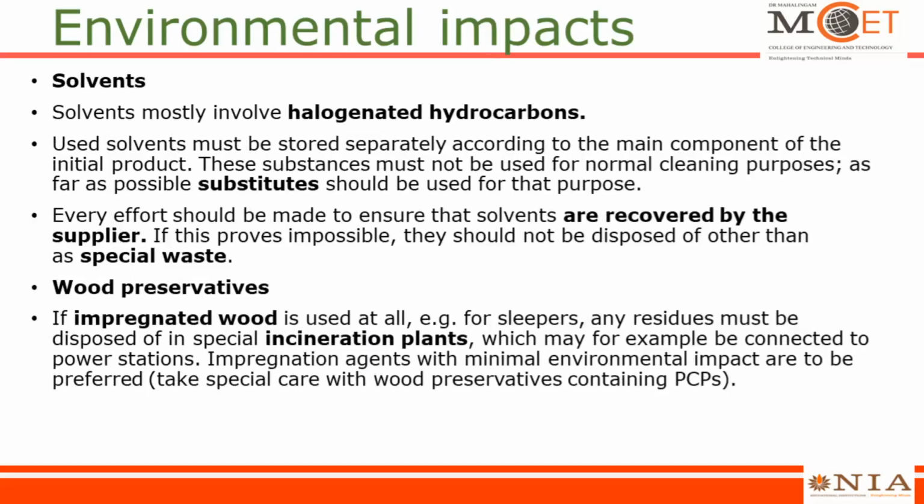Solvents. Solvents mostly involve halogenated hydrocarbons. Used solvents must be stored separately according to the main component of the initial product. These substances must not be used for normal cleaning purposes. As far as possible, substitutes should be used for that purpose. Every effort should be made to ensure that the solvents are recovered by the supplier. If this proves impossible, they should not be disposed of other than as special waste.